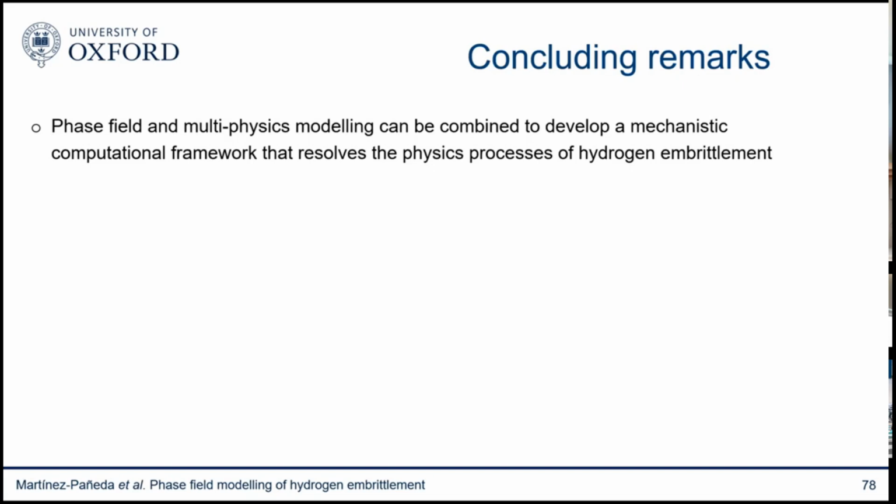And now the same goes for fatigue, right? You have fatigue frequency effects. You can no longer apply superposition. So time matters. So these kinds of things make it more complicated. But if you have a method that is in good agreement with fracture and fatigue theory, and is able to predict the transport of hydrogen precisely, which you can do because it depends only on a diffusion coefficient that you can measure in your lab, then you're able to capture this interplay between hydrogen transport, fracture, and fatigue.